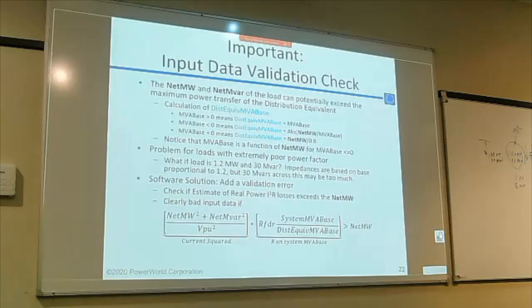In particular, this feeder impedance right here, we give it as like 0.03 plus j0.04, somewhere in there. But the MVA base of this thing is based on the megawatts up here. So the big assumption in this model is that the bigger the load is, the beefier the feeders are going to be. The problem was that this load might be 140 megawatts, and if it's 40 megavars, that's fine. Basing it on a 140 MVA base is okay.